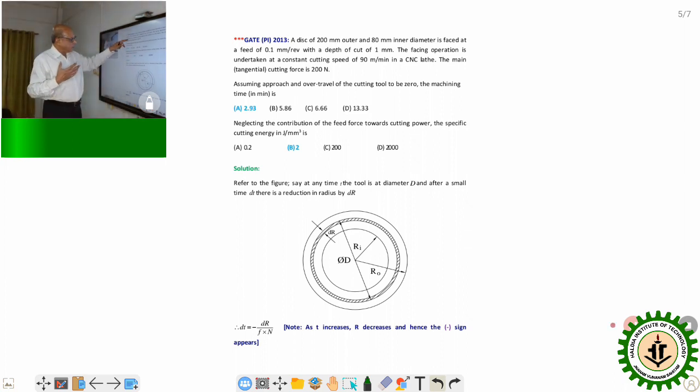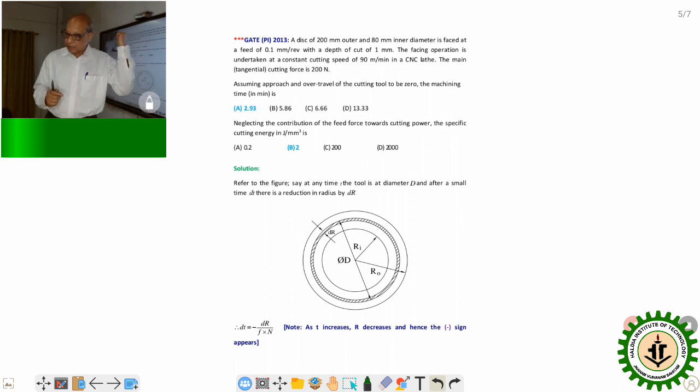There is a feature which can be invoked by incorporating suitable G code. Traditionally, G96 is a command by which it is possible to implement and maintain a constant surface speed during cutting, which is desirable for considering different tool job combinations. But in this particular context, I would like to warn you that while preparing a program during implementation,